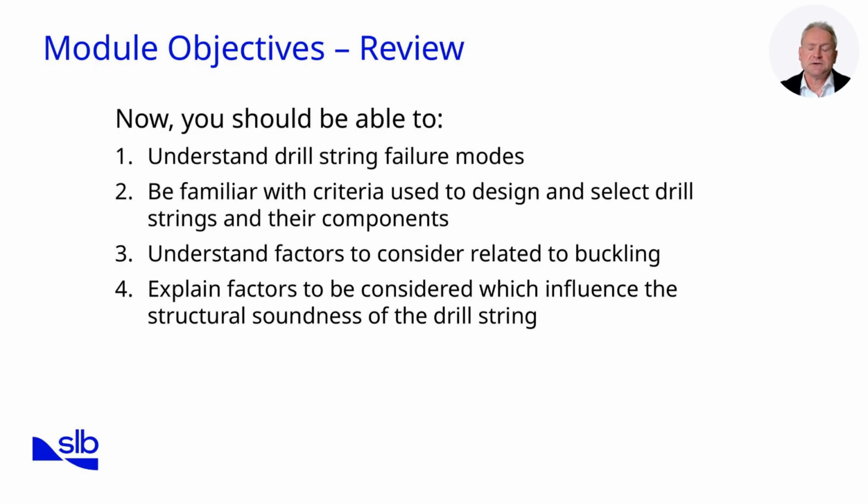Finally, we considered the structural soundness of the drill string, including casing wear. We saw how side forces, relative motion, and wear factors impact casing life, and how protective technologies like smooth flush hard banding and drill pipe protectors can mitigate damage. Together, these elements provide a complete framework for safe and efficient drill string design.